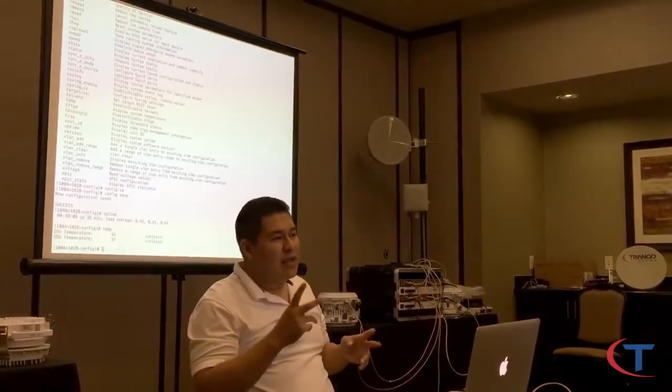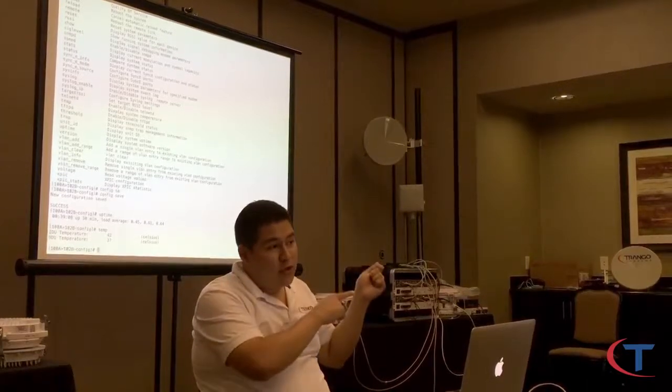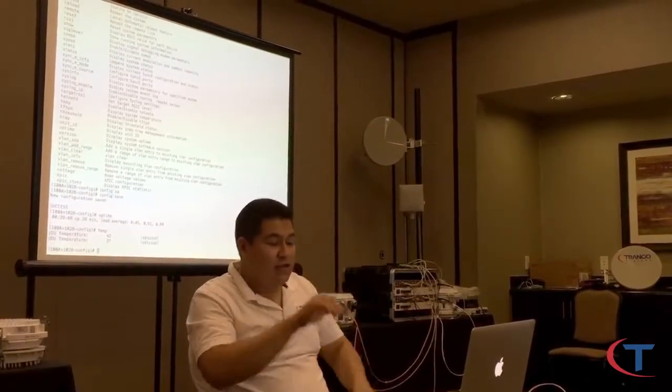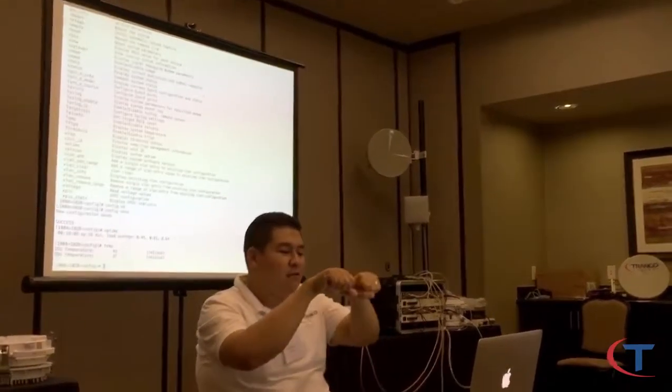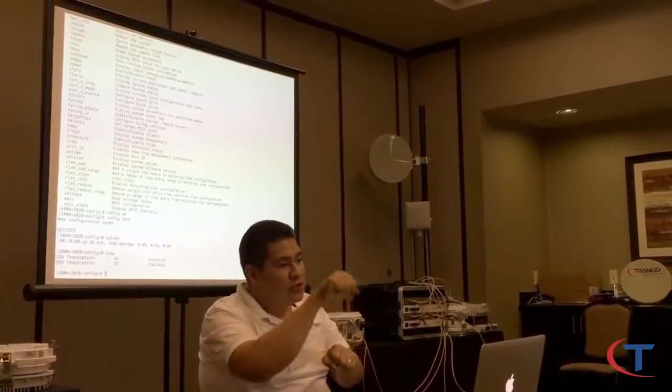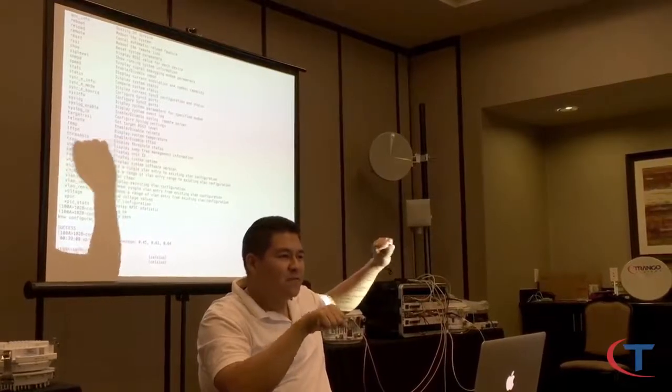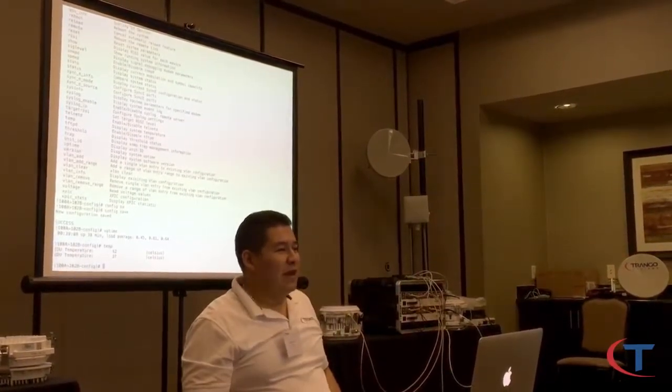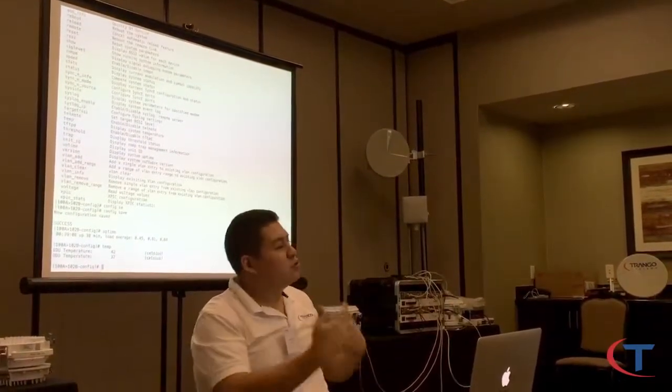What ended up being the problem was that on our installation, we had 2 IF cable runs. One from the ODU to the actual shelter. There's a transition point there, and then another cable goes to the actual rack. The cable going from the transition point to the ODU was the problem all the time, and I was blaming the ODU.